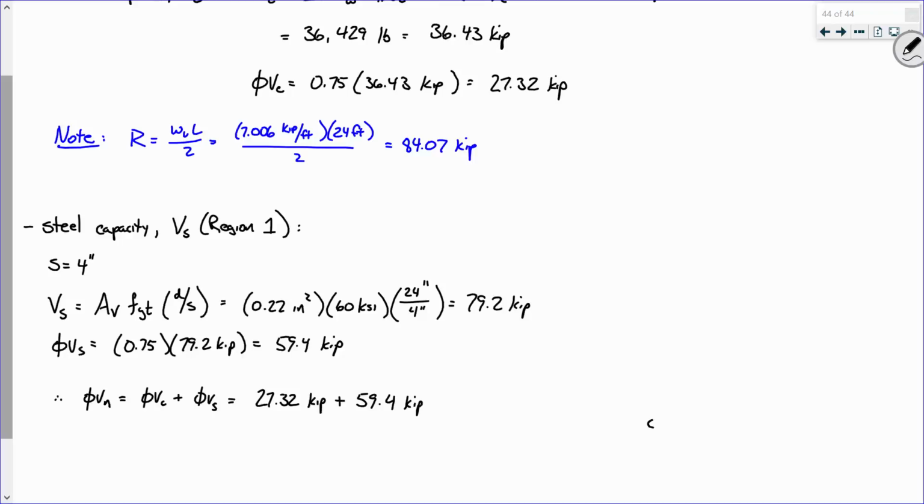Now what is that? So what is phi Vn? 86.72 kips. Now, help me out. Is that good? Just barely, but it is good, because if I compare this quantity here against this quantity right here, we're good, right?